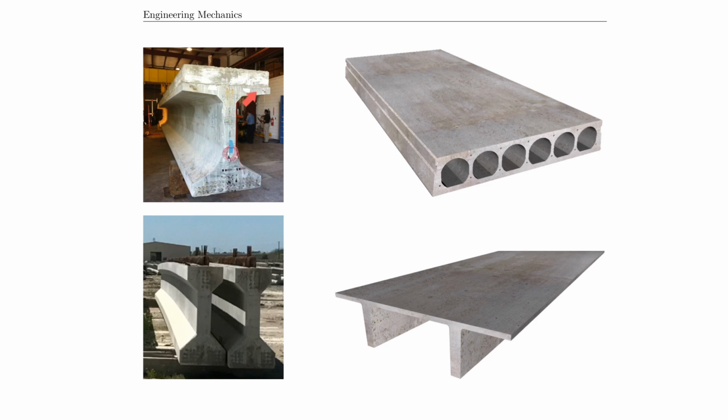So why do engineers build these? And the question that I most often get in the classroom is, hey, why do we not just create a rectangle? And the reason is due to what we already started talking about. So here is the centroid location, right? And remember that if there's a centroid location, there's also a centroid axis. So I'm going to try to draw that in here. And so the bending over that axis is important.